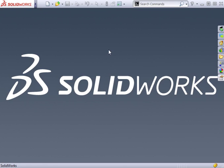One last thing I'd like to show you in this lesson are a couple of SolidWorks options you should be aware of. To access SolidWorks options, I can simply press the Options icon. SolidWorks options break down into two categories. System options control all of the global settings in SolidWorks. The document properties, on the other hand, only affect the part, assembly, or drawing you're working with.